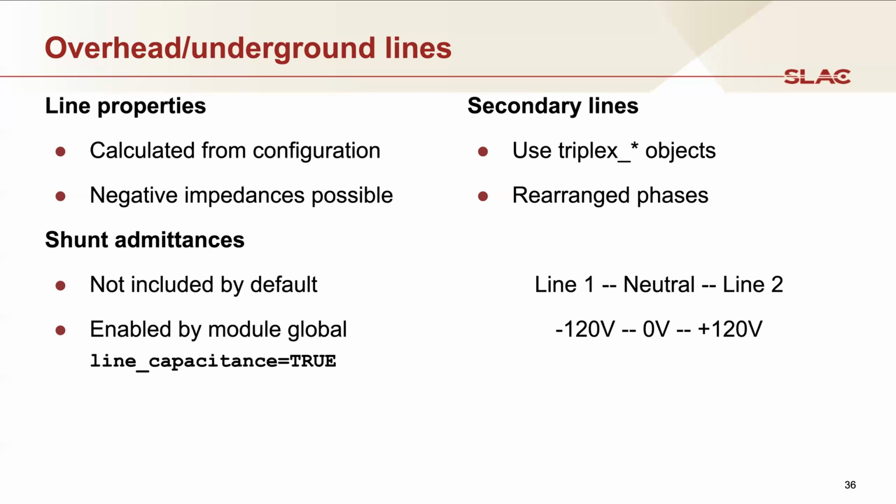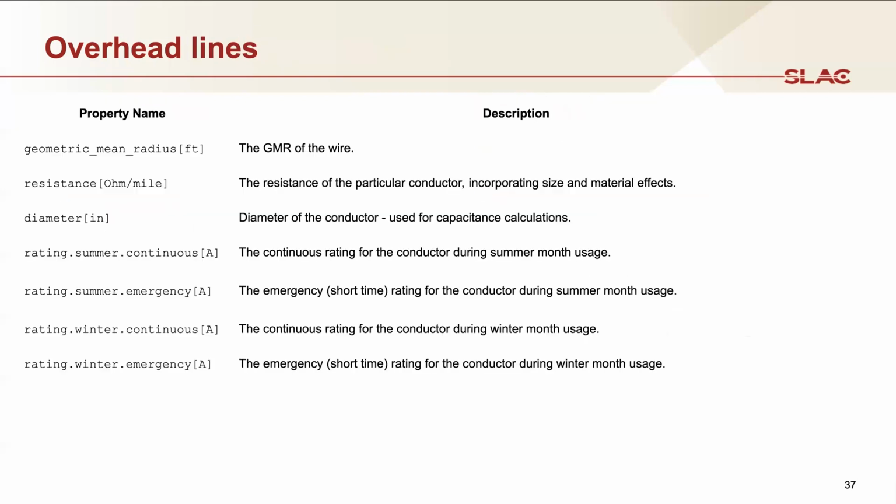Obviously if it's connected on phase A, it'll take the 180 degrees plus or minus across phase A, versus if it's on phase B, it's 180 degrees plus or minus relative to phase B. So that's just something to keep in mind about how triplex lines work.